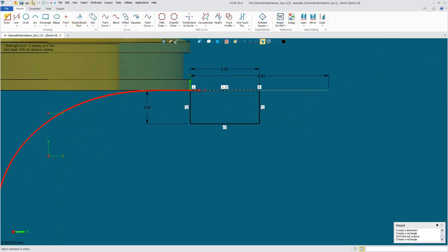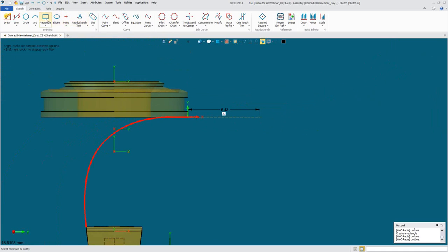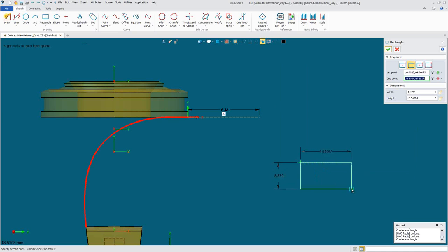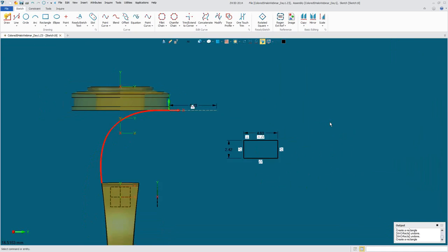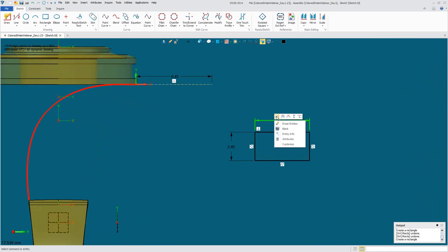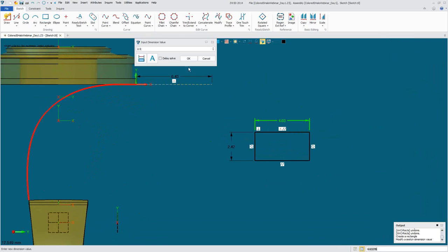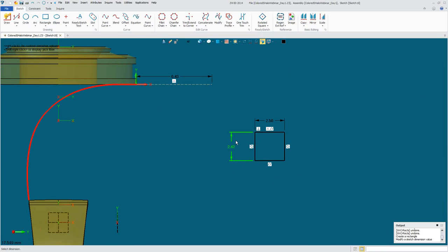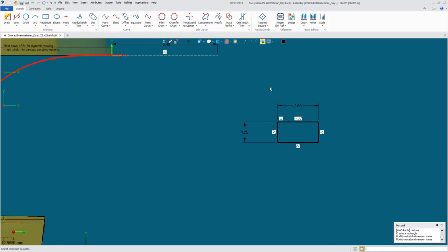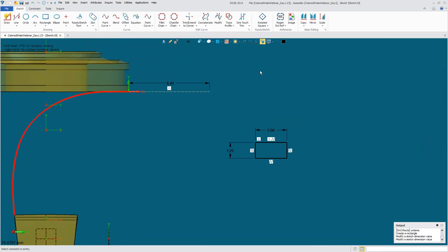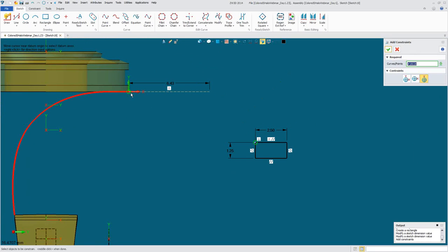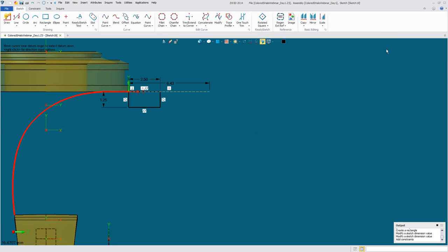Or even better yet, I'll come in over here and bring the size in at this area, where there's no inferencing lines. Dimension it here, 2.5. Dimension this, right click, 1.25, okay? And right click, create a lock with this endpoint and the origin. And we want a point-on-point lock, bingo.